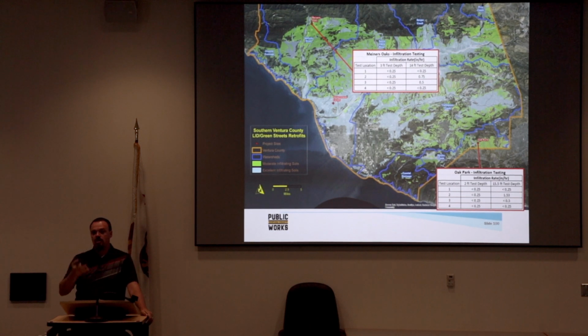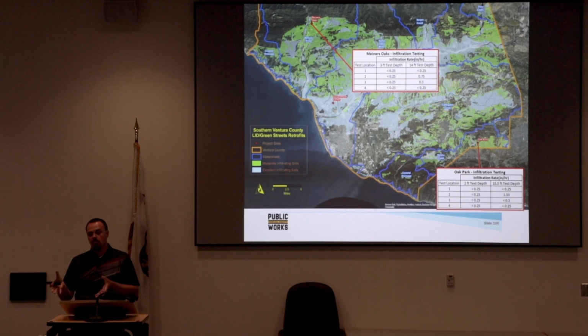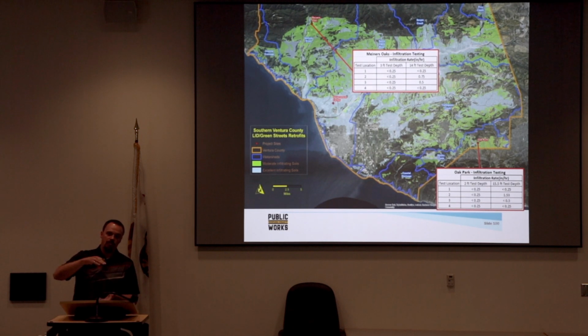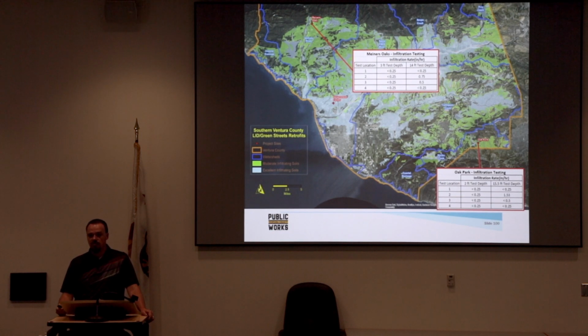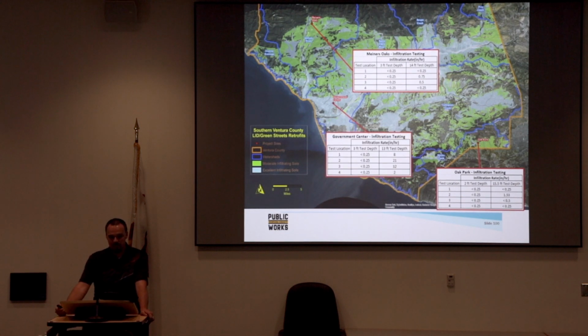We're not doing the full section, but from comparing those areas to the borings we get from the geotech that pulls out and says, okay, for this area we have clay, this is a silty loam, we can identify the variability in the soils, and pretty much it was clay all over. It's never a good sign when you pull out the drill bit and it's smeared with clay. It's always a little bit of a downer.